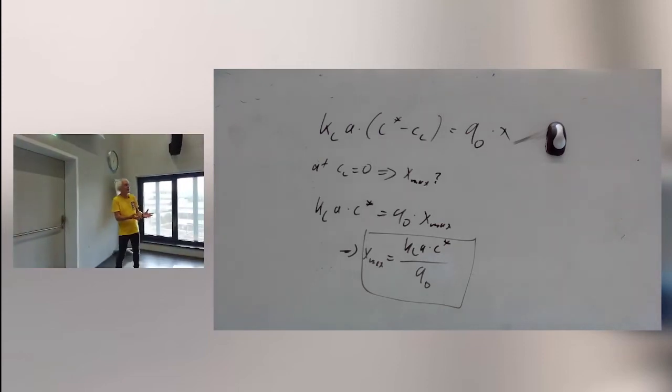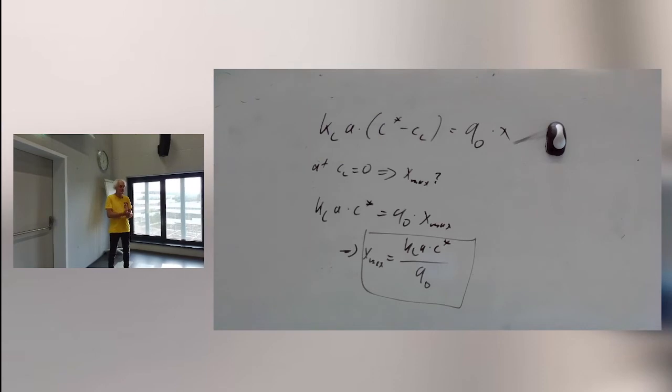As soon as my oxygen concentration gets limiting, I have no more exponential growth, but I still provide oxygen to the cell. Of course, they then can still grow. However, no more exponentially. Yeah? And therefore, of course, my x equals x0 times e to the mu t, for example, is no longer valid. So if I want to calculate batch times and so on, I cannot do that anymore with these equations.